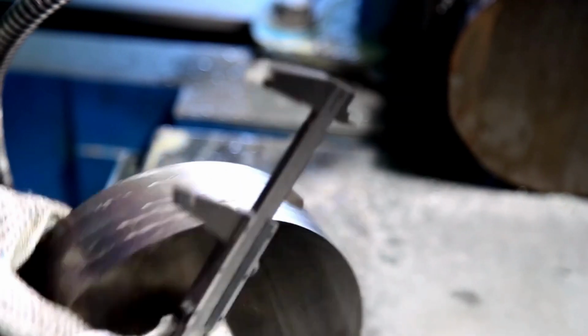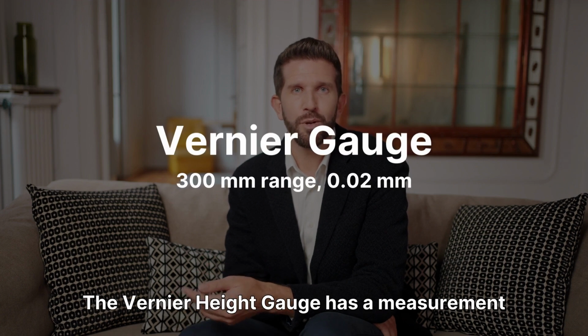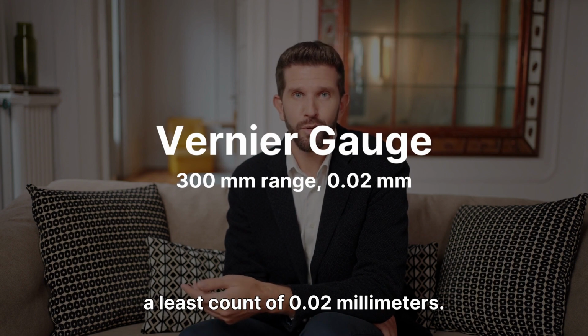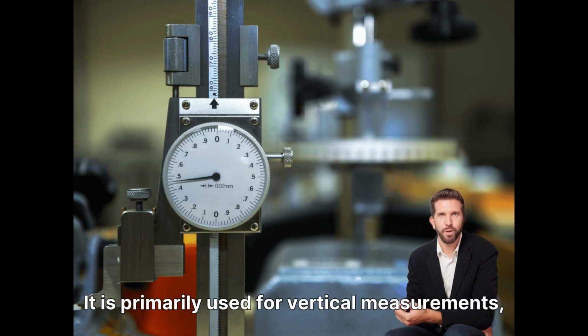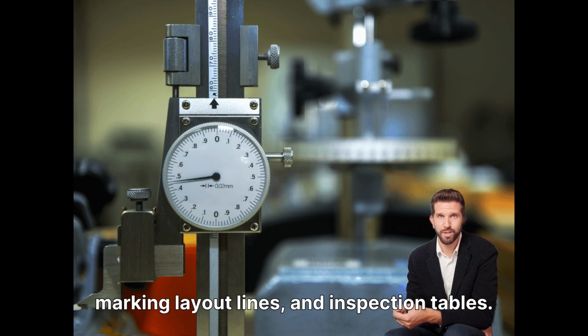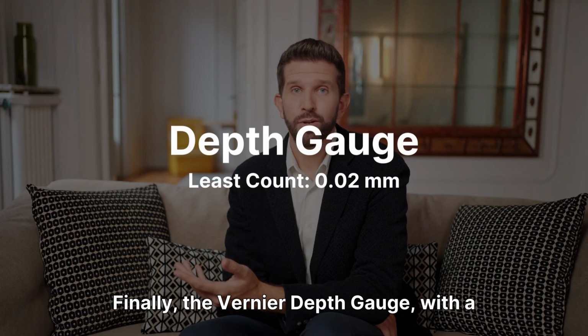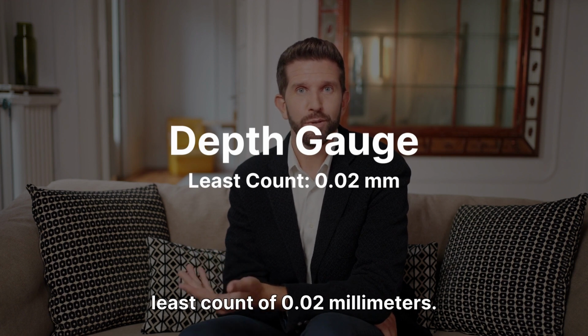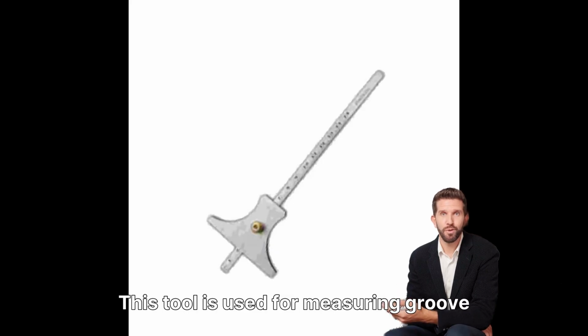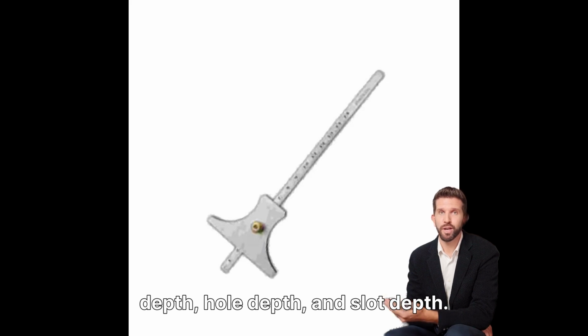in workshops. The vernier height gauge has a measurement range of up to 300 millimeters and a least count of 0.02 millimeters. It is primarily used for vertical measurements, marking layout lines and inspection tables. Finally, the vernier depth gauge, with a least count of 0.02 millimeters. This tool is used for measuring groove depth, hole depth, and slot depth.